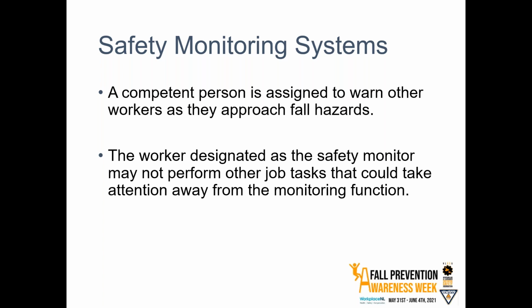Now, there are some situations where this may literally be the only option that you've got, and the thing that comes to mind in particular is roof work. For example, if I was applying a new torch-on to a roof. Torch-on is a type of shingling material. It comes in big rolls or sheets that get applied to the roof using mastic, this black goop, and heat helps it all seal together.